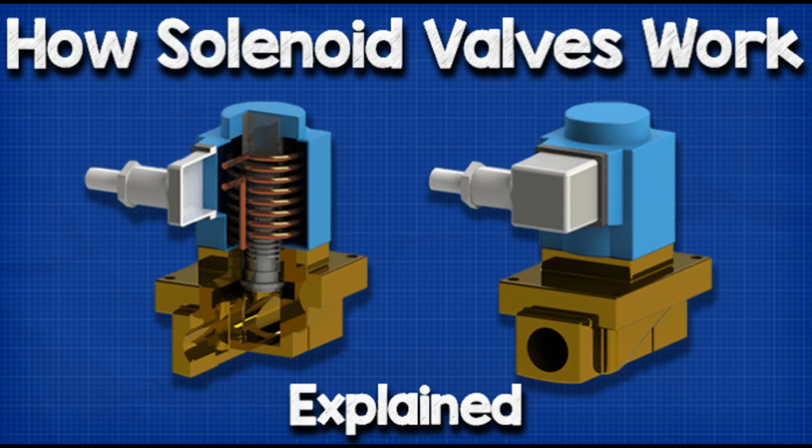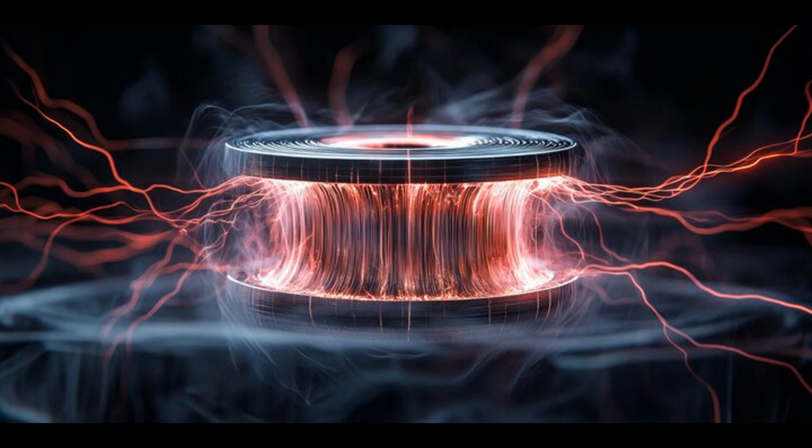5. Locks and security systems. Electromechanical locks. Solenoids are widely used in security systems to control locking mechanisms. They are found in door locks, magnetic or mechanical locks that can be activated remotely. Safe locks. Solenoids control locking bolts in safes, allowing for remote unlocking with keypads or biometric sensors. Access control systems. Used in electronic security systems to control the locking and unlocking of doors based on authorized access.